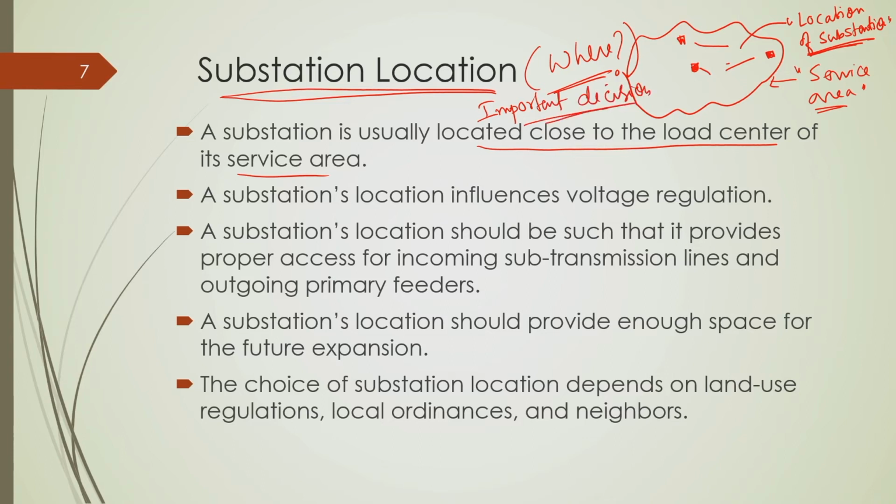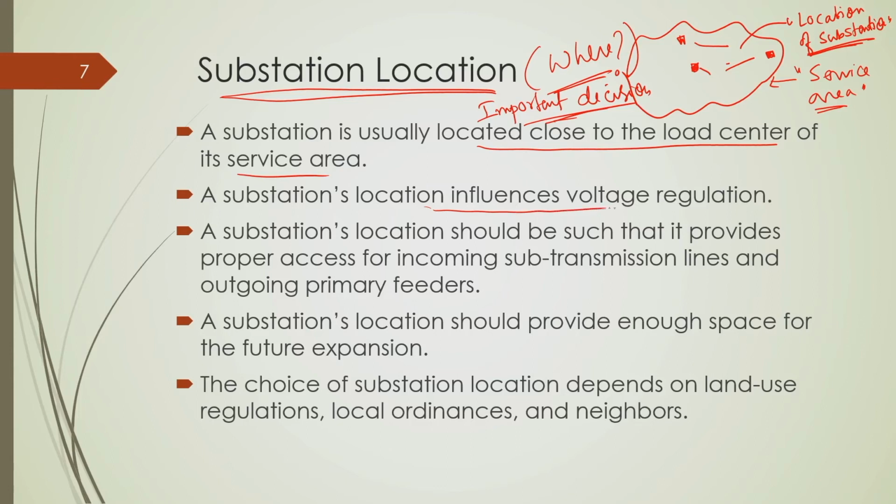Now, apart from that, what would be the capacity of the substation? That is also an important decision. Basically, substation capacity depends upon how many transformers you have and what the capacities of the individual transformers are. Substation location also influences voltage regulation.